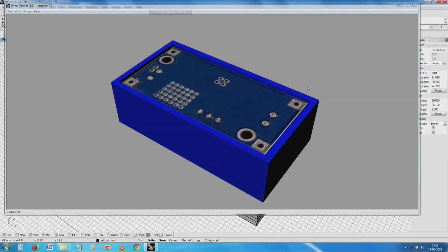I have to decide whether I give a relief on the heat sink, and then I have these 2 mounting holes. Now, I can use the heat sink, and in this case, no, this is where the via holes are there, and the manufacturer has recommended that we use the via holes, put a little bit of heat sink paste and just clamp it down with sufficient force.